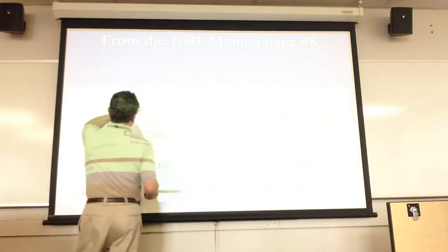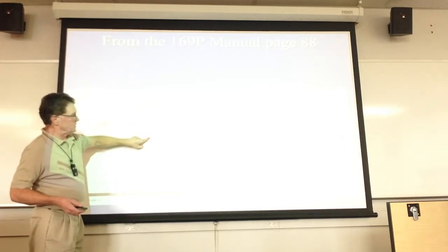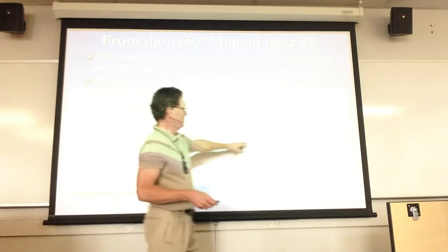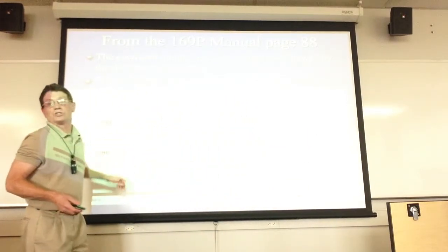Just these couple of slides explain what's going on there. So again, the status register on port B. This is the I/O address. This is the physical address in memory. I/O address, physical address. They are 8-bit registers, obviously. If you go down and look in the LSS file, you'll see that these are set up. 3, 4, and 5 are set up at the proper I/O addresses. It forces it. That's just the way it's set up.